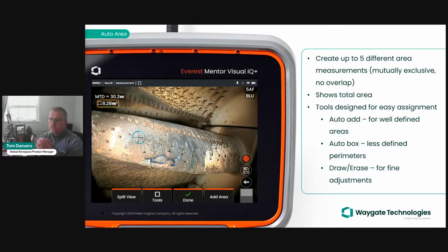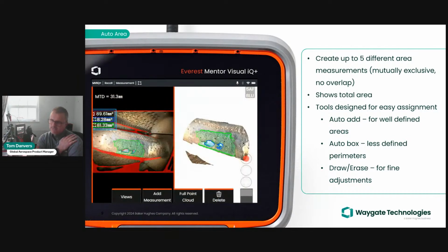As you select another tool, and you saw me select single select, the whole blade illuminated. I intentionally selected the wrong tool, because if you go down to the box tool, trying to make sure that you're drawing the right perimeter, in this case for oxidation, the box tool is more appropriate.